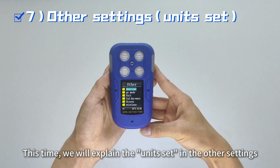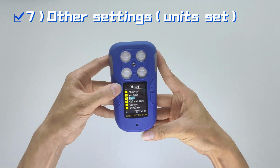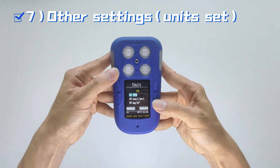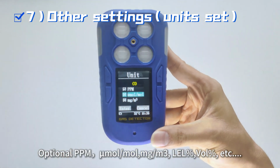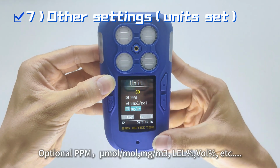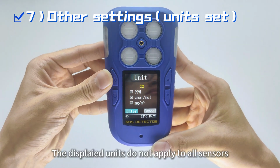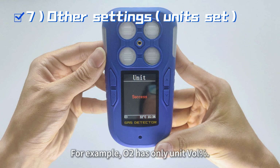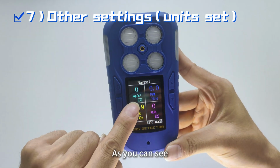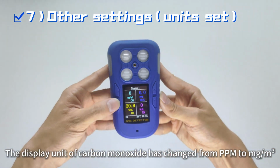This time, we will explain the units set in the other settings. It is used to switch the concentration unit of the measured gas. Optional units include ppm, micromoles per mole, milligrams per cubic meter, LEL percent, volume percent, etc. The displayed units do not apply to all sensors. For example, O2 has only the unit volume percent. As you can see, the display unit of carbon monoxide has changed from ppm to mg/m3.